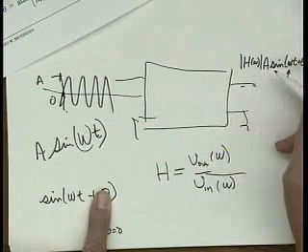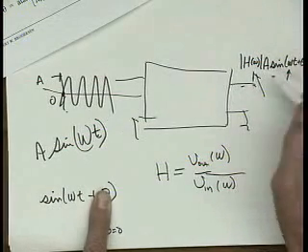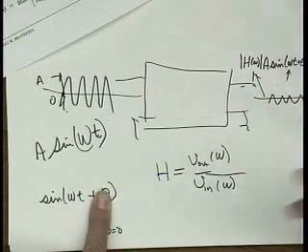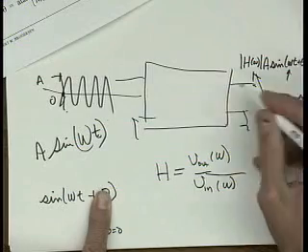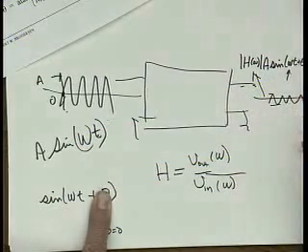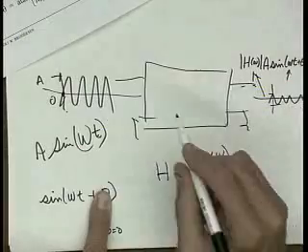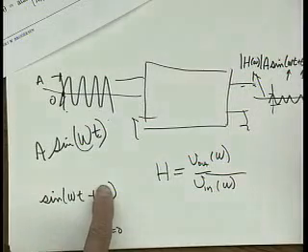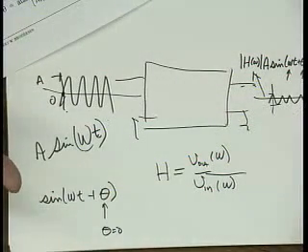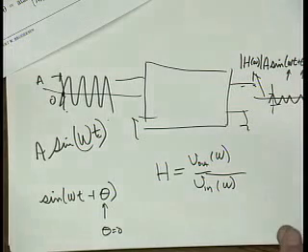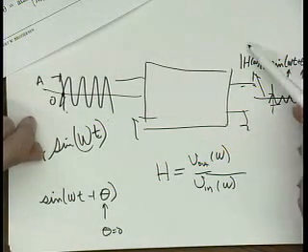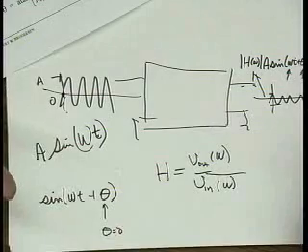So we now have two things we have to calculate. We've got to calculate this magnitude change. So what comes out the outside here is something that's maybe reduced, it may be increased in amplitude as a function of frequency. Depends on if you have inductors or not. So the amplitude will change and the phase will change, in other words, where it crosses zero. So this phase shift. You may think, wow, why do we care about this phase shifting? That doesn't seem too important. That's the stability problem, it's all to do with phase shifts, okay? So stability is why we have to worry about this theta thing. So we will calculate amplitude and phase just like they're equally important.